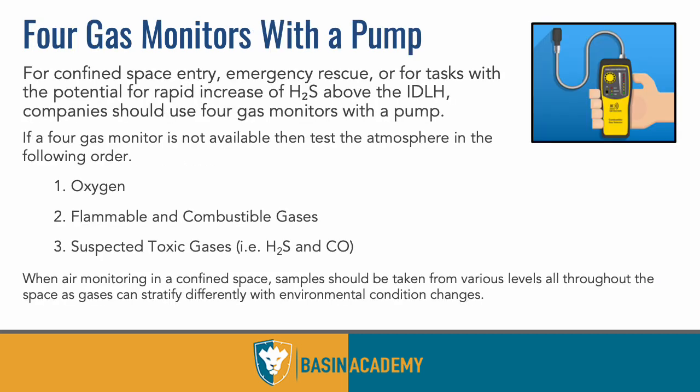So then you have 4 gas monitors with pumps. You can also do single gas monitors with pumps. Again, there's a lot of configuration, but essentially they're also called direct reading measurement devices. The end of that hose has that black tip, and it's going to draw air into this monitor and read it from an area away from you, so you're not right in it. Some guys use their personal gas monitors for this. It's not effective, doesn't work. The amount of time necessary to read, depending on how quickly you're moving that around, may or may not work.